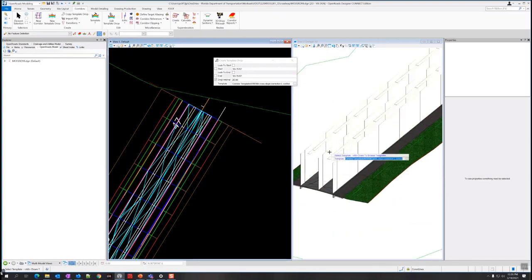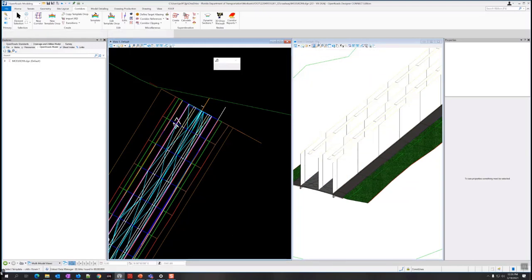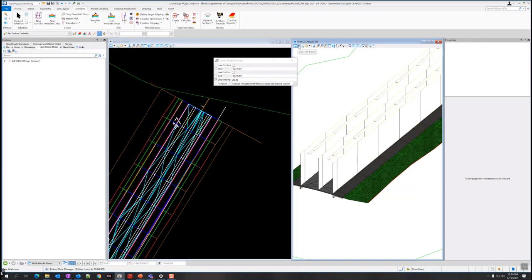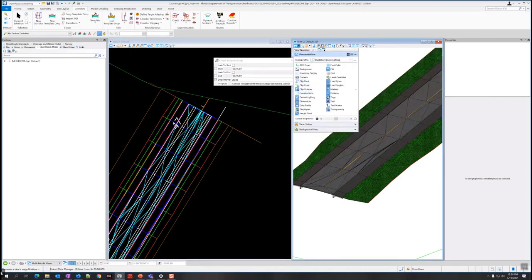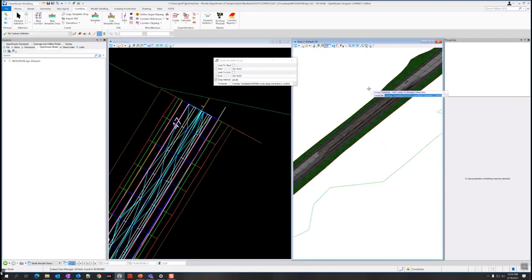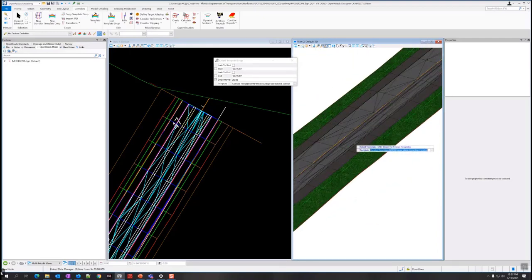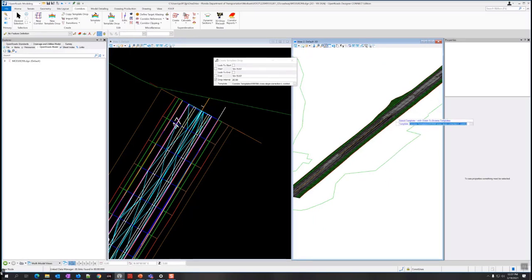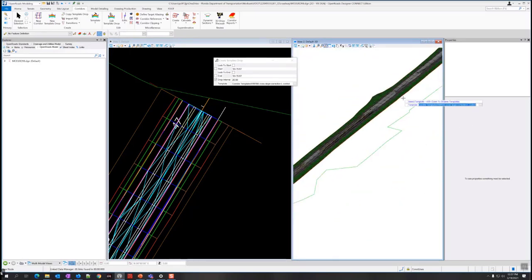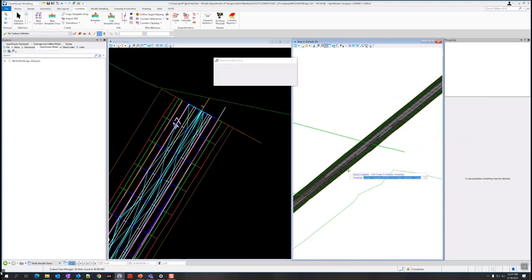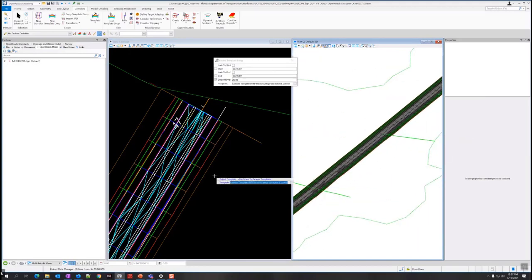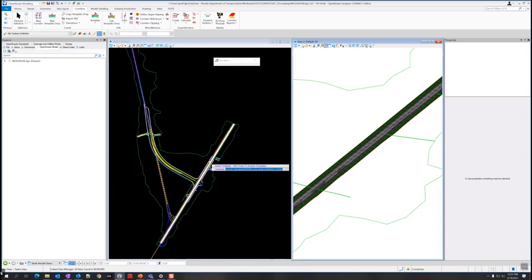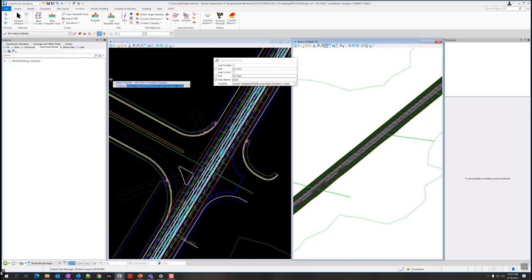These are end conditions looking for the existing ground. That'll help it out with doing the end conditions, makes it easier to be able to do reports on the cross-slope correction. So if I do view attributes and turn off constructions or use the F7 shortcut, you can see something was built. So this got resurfacing in the middle, and then it's got some other sections here. But it's not quite what it needs to be. Not yet. So we're going to have to add a bunch of corridor references in here first.